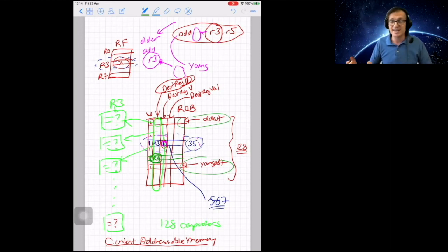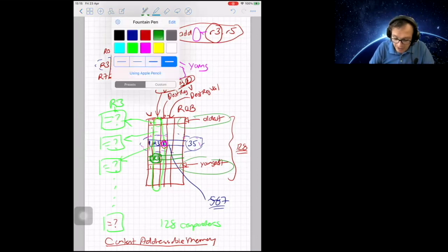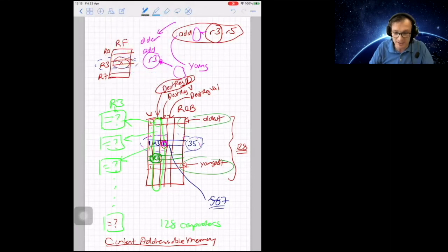Basically, this is a content addressable search, but it's an ordered search also. And the comparators are actually priority order comparators. So it's not an easy search, if you will. Okay, so hopefully it's now clear how the register file and reorder buffer operate. Let me talk a little bit more about how this operates because it's going to be important. So we search from youngest to oldest and take the first match. Yes, absolutely.